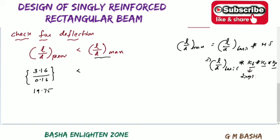For example, if we are designing a doubly reinforced beam, it is necessary to check the modification factor for both conditions from the graph, that is tension reinforcement and compression. If we are designing flanged beams like T and L, at that time you can check the modification factor kf also. That is the reason: here I am designing only a singly reinforced beam, therefore I am considering L by d basic into its modification factor, and in that modification factor we check only tension reinforcement.